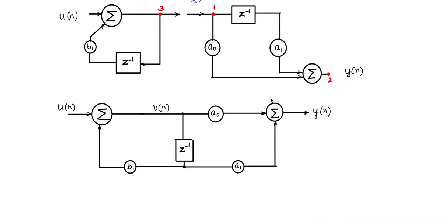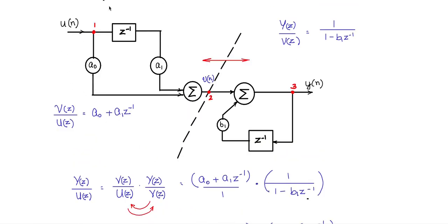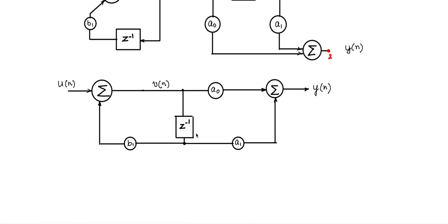This is the first order filter which is normally implemented because you need only one memory location in the data memory space of your program. But this block diagram is more intuitive, especially for understanding the concept, while for implementation this one is more optimal in terms of data memory usage, and we will use this.